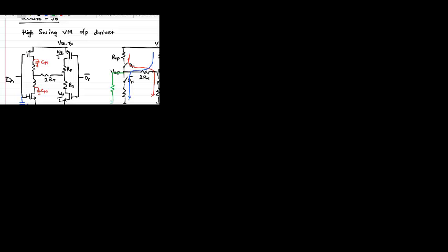So consider when the current is flowing from R up on the left to R down on the right. In this case, if you want to have a lower swing, you can bring the left node down by using a resistive divider, and you can pull the right node up, so you can get a lower swing. Do you get that? Okay, let me go through it in more detail.